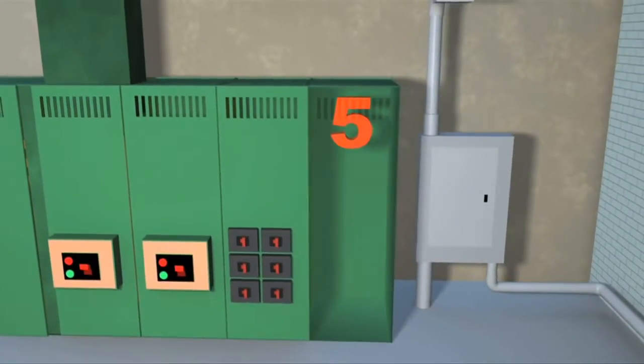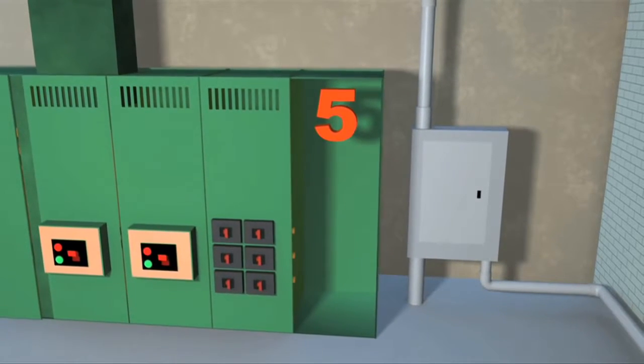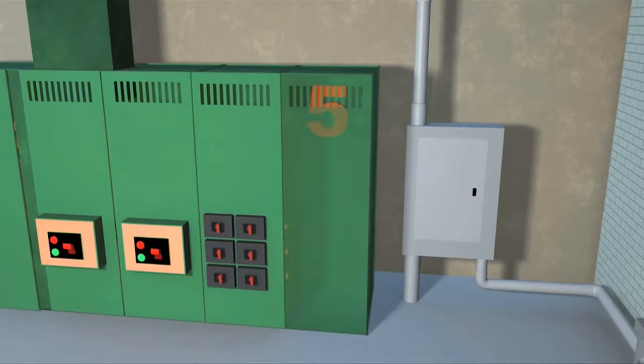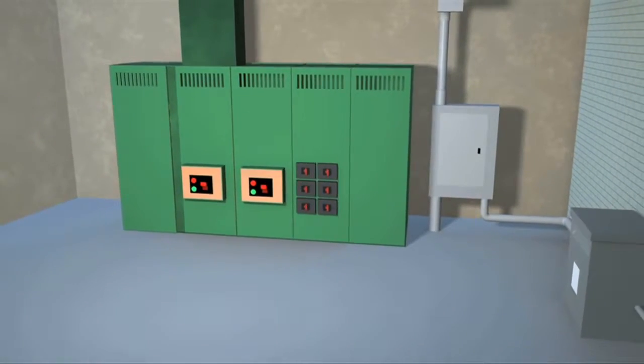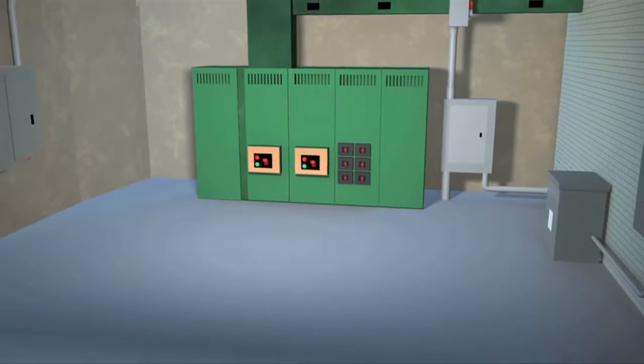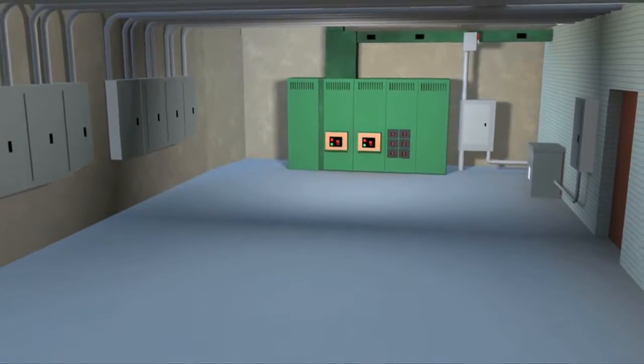The fifth and final section of this switchgear is empty with a solid or blank panel cover. This could be a spare section for future expansion. A blank front does not necessarily imply that the section is a spare. It is important to ask what is the function of this section and is there something in there that needs to be tested.